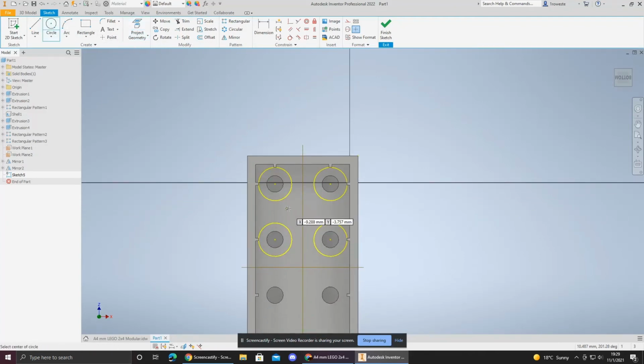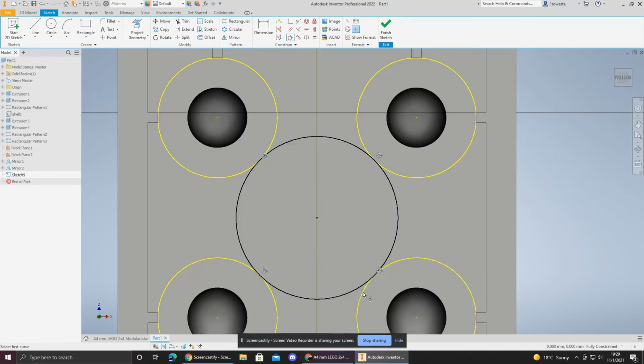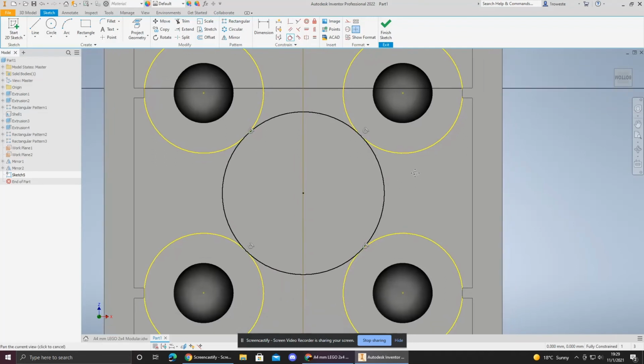We may now create a circle at right about anywhere within this at any size, seeing as we will soon be constraining it. You can just hit enter. Now we will select the constrain tangent tool and simply constrain each of these circles to one another. The 4th one is unnecessary, however redundancy will allow you to double check that everything has been perfectly positioned. If the constraint of the last 2, so the 4th and of course the 1st circle, is rejected, something is amiss.